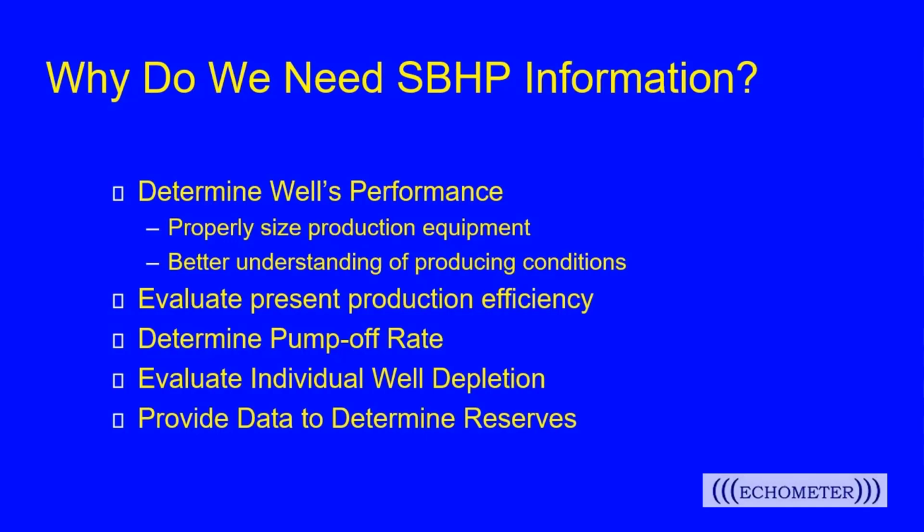It'll give us a better idea of our production efficiency, help us size the equipment, and determine, in the case of a pumping well, what rate we would get if we'd pump off the well, or on a flowing gas well, what rate we could get if we could deliquefy the well. In addition, we can determine depletion. We can see how the static bottom hole pressures are changing over time. And that's a good number to know.